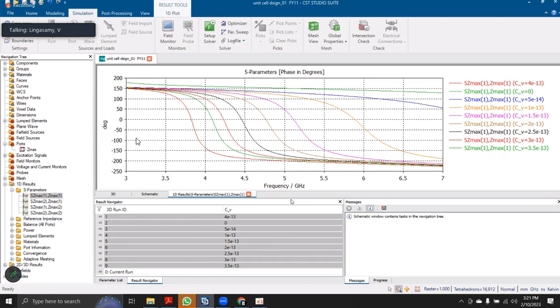One is, for example, radiation pattern characteristics. Actually there are many factors. One is, if you are going for large inter-element spacing, then you will have a problem in generating multiple beams. And also beam width will have an effect, because if you are increasing the spacing, then you have to apply appropriate weights to control that.